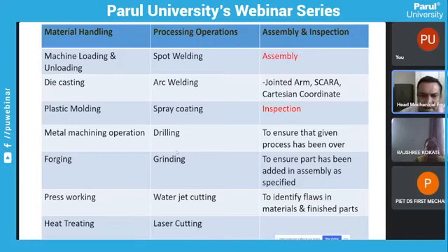That kind of scenario can be thought of, and people are working in that direction also. For processing operations, as you have seen in the video, after welding at any location we would like to go for inspection, or if you want to perform welding precisely, a robot can maintain a constant velocity. A human hand may have jerky motions, but a robot will be jerkless, with a pre-decided feed rate. With that, spot welding, arc welding, spray painting, or any kind of cutting operation can be performed using robots. In Indian industries also, people are using SCARA or joint arm robots. Normally KUKA and FANUC robots are widely used in industrial areas of Gujarat. At many places in Makarpura GIDC and Vidyanagar GIDC, you will find robots like KUKA and FANUC control.